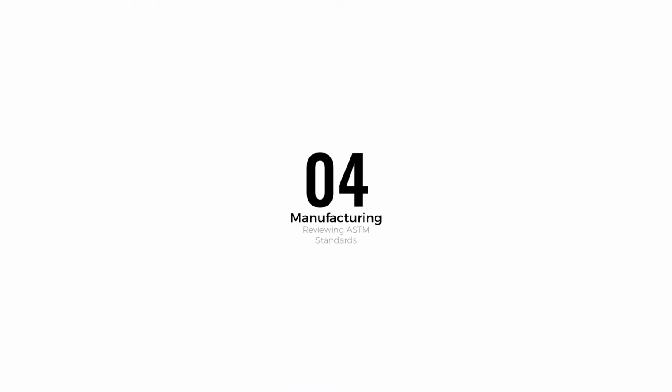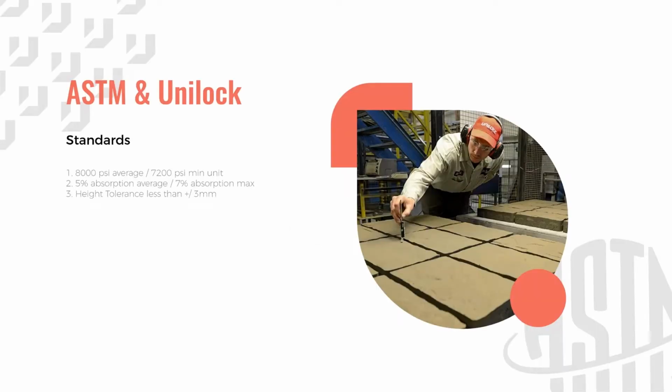Section 4, Manufacturing Standards, Reviewing ASTM Standards. ASTM standards require our pavers to have an average of 8,000 pounds per square inch of compressive strength, with a minimum of 7,200 pounds per square inch. The standards also require that our pavers maintain an absorption average of 5% with a maximum allowable amount of 7%. Height tolerances cannot deviate by more or less than 3 millimeters of the intended height in order to comply with the ASTM standard.